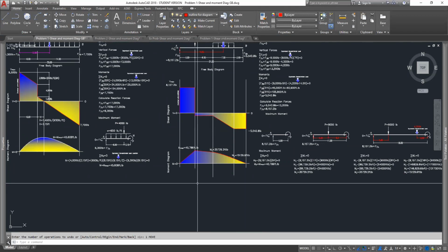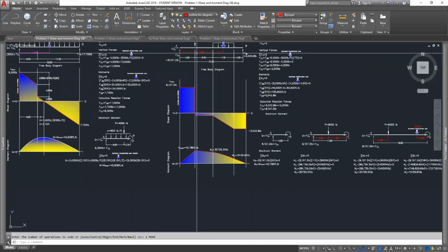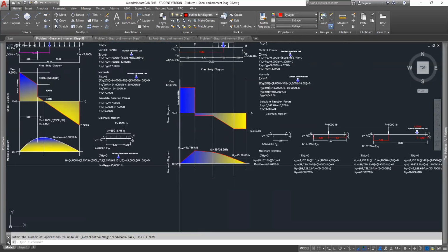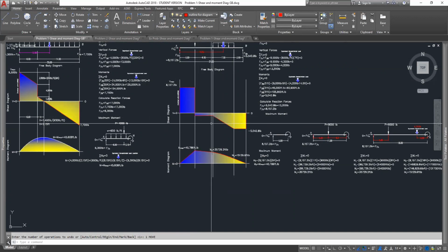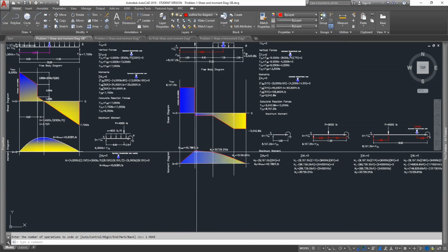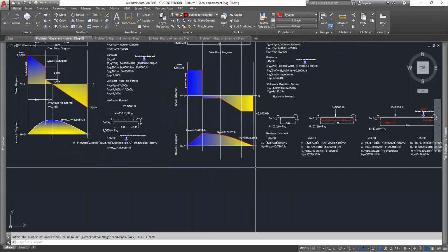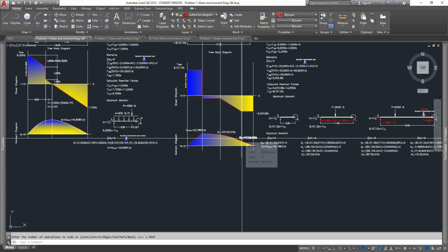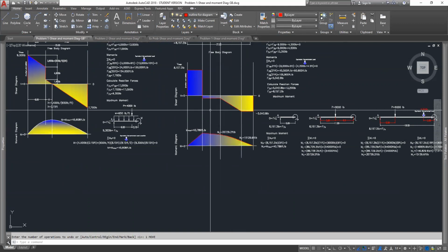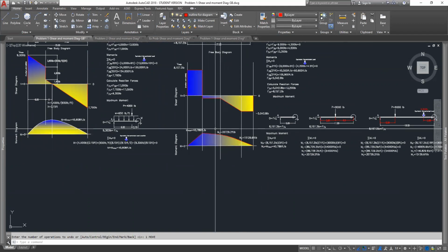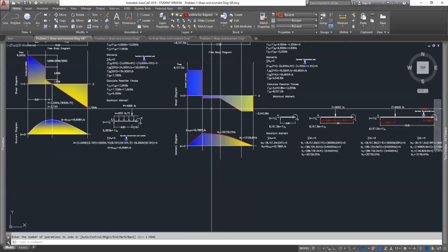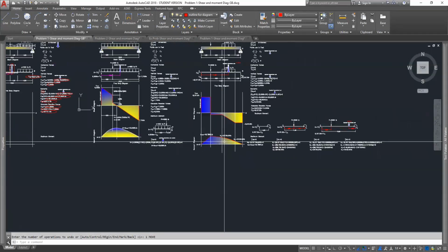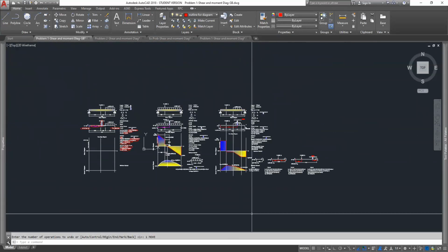Now the last problem, problem 2, is super easy. It's only concentrated loads, right? So you don't have to worry about this. All you got to do is vertical, horizontal, down, horizontal, up, and that's about it. As far as the moments, you know they're all going to be straight lines. You will not have a parabolic curve or a curve located at that point. What you do have to do, though, is to show me where your moment changes direction. So this will be coming up, go to the next event, then it'll start coming down from the point of maximum of 0 shear, which will be your maximum moment. All righty?